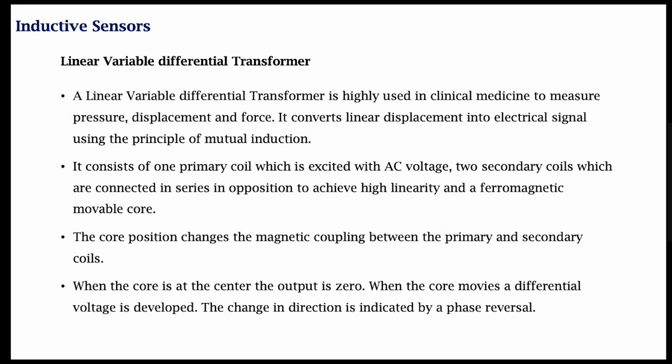If we are measuring the differential output between the two, and if the core is exactly at the center, the differential output between the two will be exactly zero. But when the core moves in either of the two directions towards either of the two secondaries, there will be a greater voltage induced in the secondary towards which the core is moving. If the direction changes, there will also be a phase reversal that you can observe in the voltage.